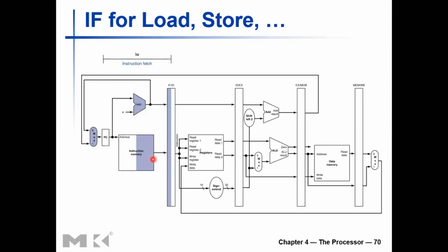So in the single cycle implementation, you need to make sure that all operations are completed, and any result to be written into either the register file, the program counter, or the memory for that matter, is ready by the rising edge at the end of the clock cycle.